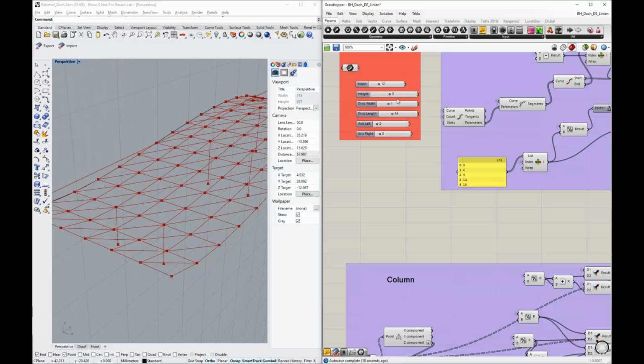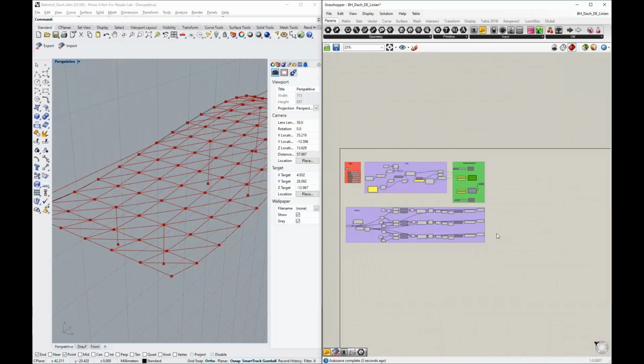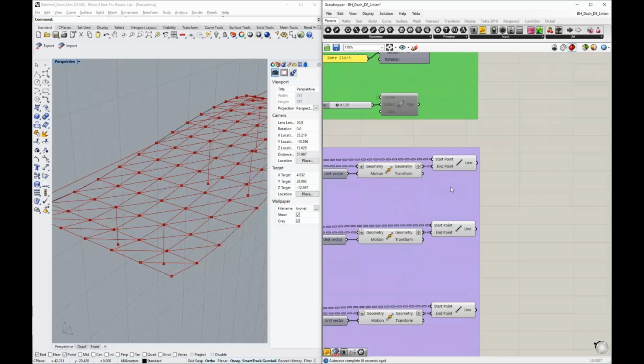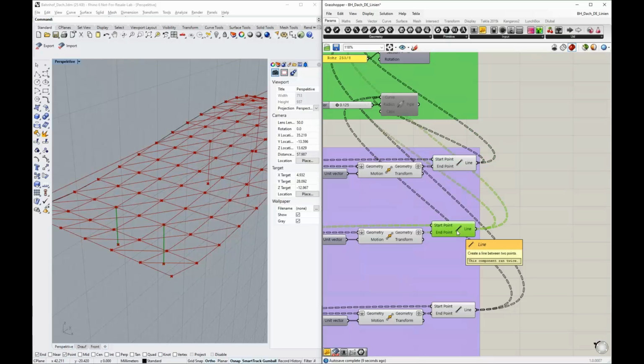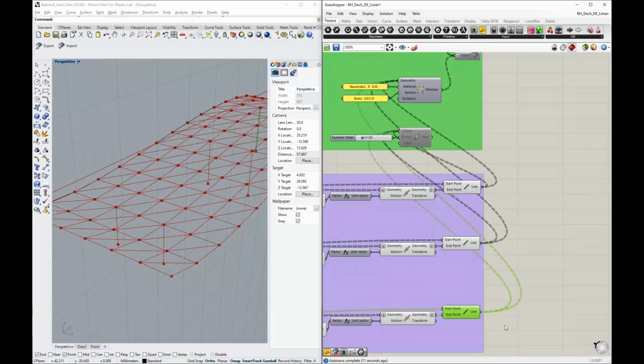And the other goal was to have control over the height of the structure. Again, the result of this algorithm were 3 pairs of lines. And I created another member component. Here I defined a different cross-section for my columns, and I also plugged it into my export. Now I can show you what will happen when we run the export.